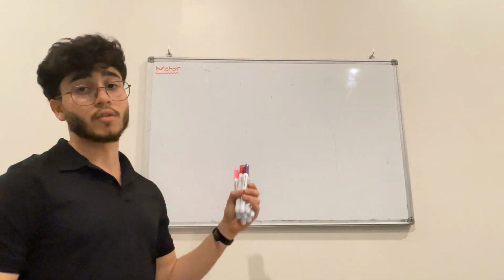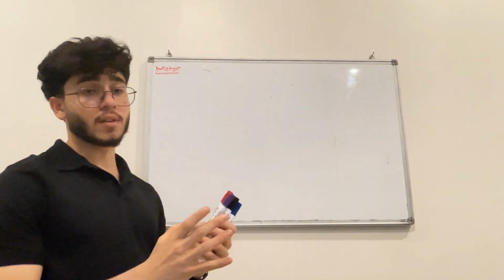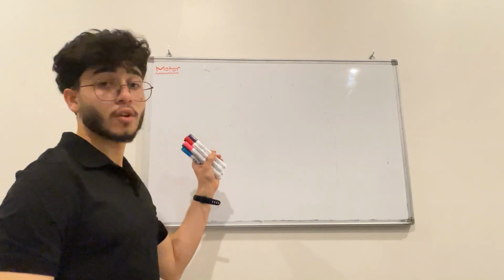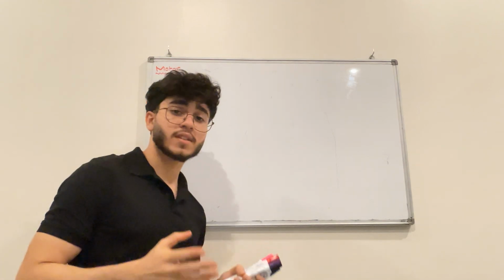In this episode, we're going to start talking about the motor, the electric motor. We're not going to jump directly to the diagram of the motor. We're going to start from the front view of a solenoid, deep dive into that, see what the motor looks like, and understand the purpose of the motor. We know a generator generates electricity from kinetic energy, kinetic to electrical, but the motor is the opposite. The motor does not do kinetic to electrical, the motor does electrical to kinetic. It converts electrical energy to kinetic energy, or energy of motion.